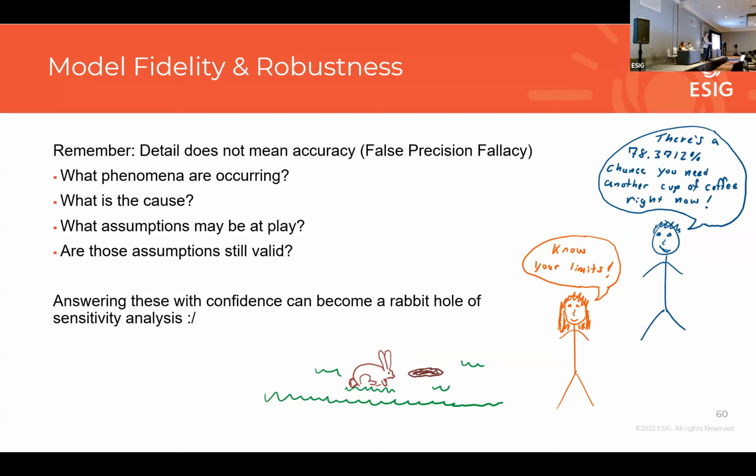What is the cause? We think it's this model or this aspect of it, but we used a Bergeron model instead of a frequency dependent model. Is that playing a role here? Okay, we think so. Do we care? Is it important? Well, yes, it could change the results of the study. All right, we've got to go back and change that line representation and rerun, maybe some subset or maybe the whole thing, right?